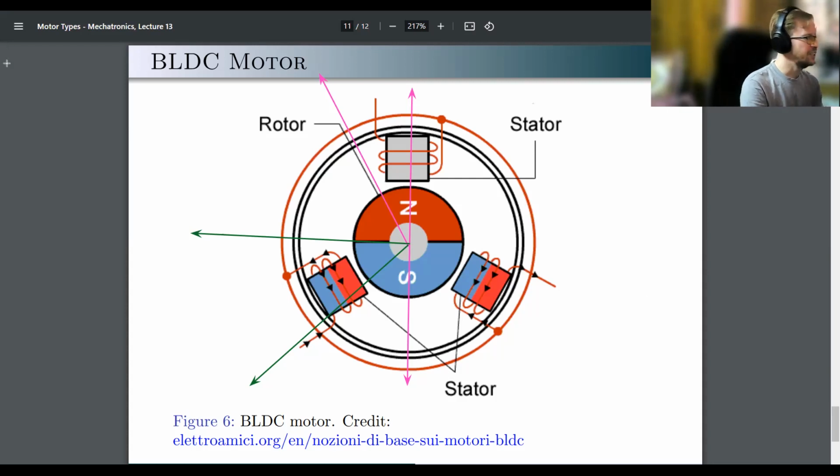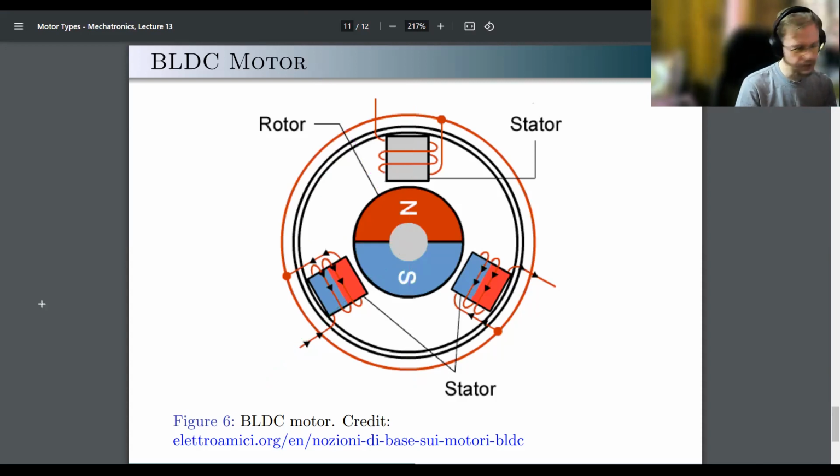Of course, all of this is nice, but also a whole big part of why brushless motors are so widely used is because the design is very specific. They are very lightweight. They're built to dissipate heat fast. For drone design motors, and even for modern motors that are used in walking robots, often the entire upper half of the motor is rotating because the rotor is not a cylinder inside the motor.